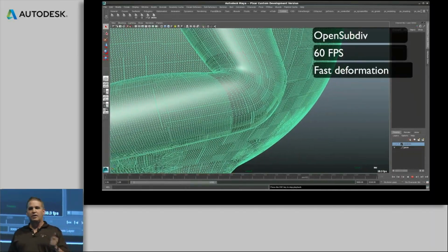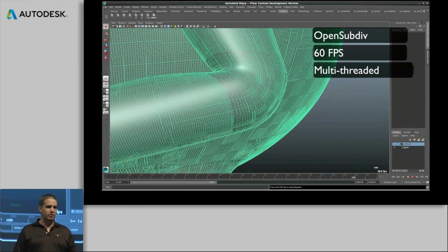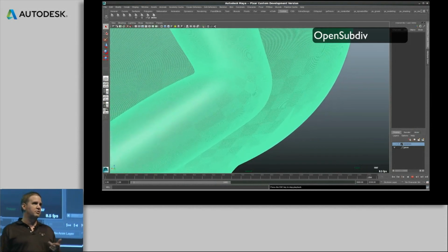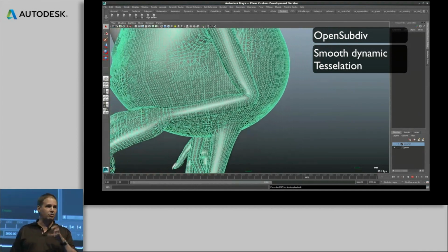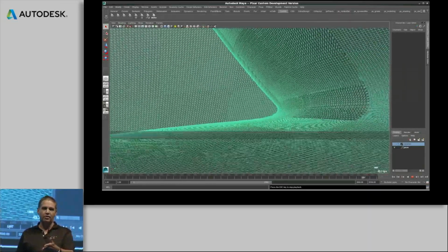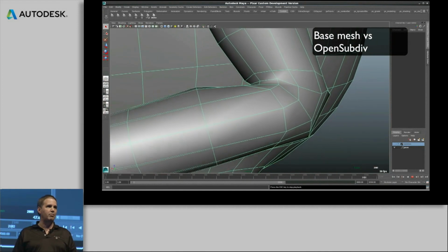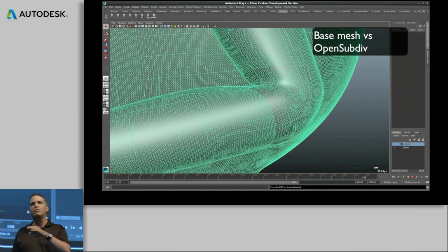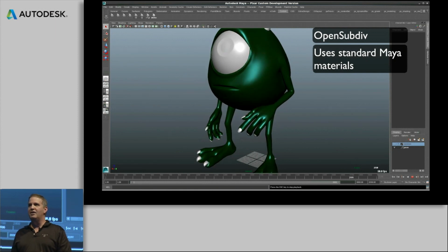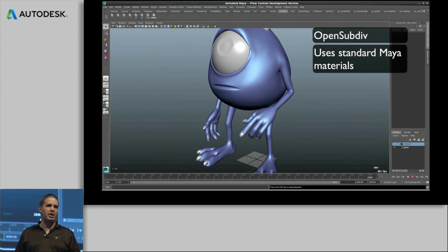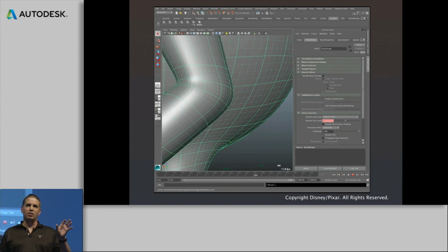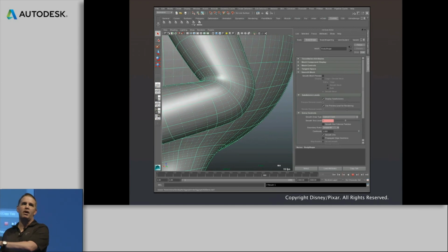Okay, now we're going to turn on OpenSubdiv. 60 frames per second, we're subdividing to whatever level we need to make it look good. We zoom in and out, we'll go to level 6, we'll have a few million polys on the screen. They get so dense that it looks like a limit surface. It's just a cage subdivided that fast. And yeah, when you get that close and you turn the subdiv up that high, it'll slow down a bit. But we are at 60 frames a second for this level of quality, which is smooth at basically any camera angle. And here's the thing I want everyone to understand, the thing I keep harping on over and over again. When you turn on OpenSubdiv and you're drawing it this way, the only thing Maya knows about is the 10,000 faces of Mike, period. The 6 million faces being drawn are known only by the GPU. We keep the low poly count on the CPU. We keep the high poly count on the GPU.